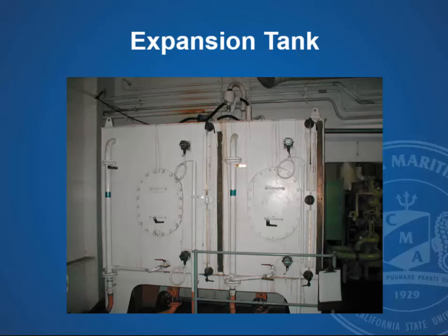Internal leakage can be a little bit difficult to determine. If you have conventional purifiers like we have on the Bear, you can look at your purifier heavy phase discharge, and you should never see water coming out on a continuous basis. So your purifier would remove any water that was coming into the crankcase, and it would remove it from the oil, and you would see water coming out of the heavy phase, and that would tip you off that there is a problem.